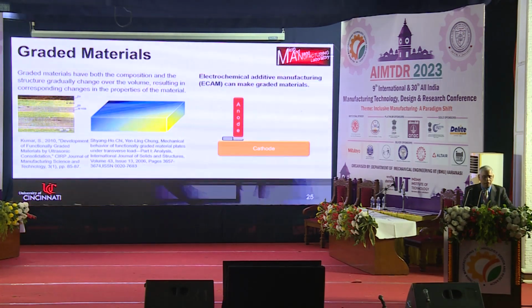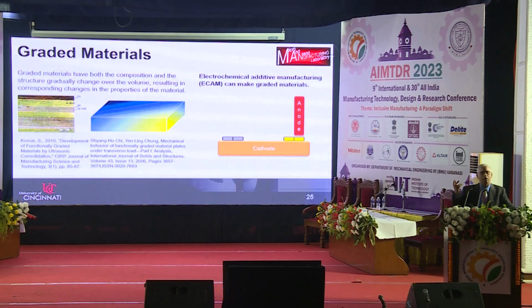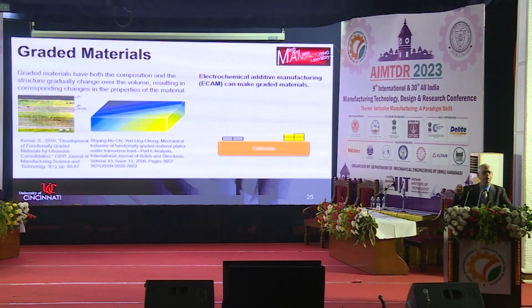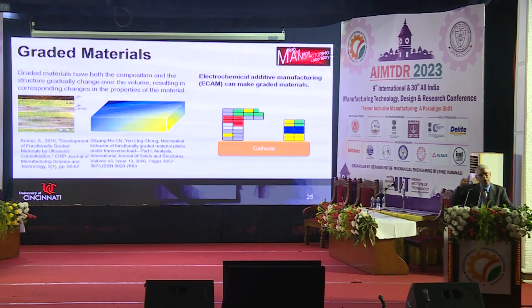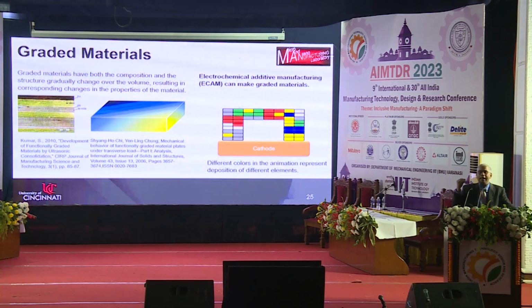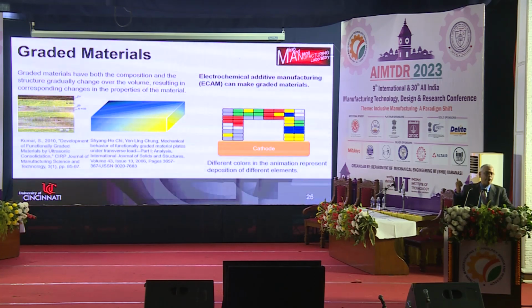So I can move my anode to whatever location that I want. And if you look at the color changing there, I am symbolically telling that is a different material, right? So I can use this concept, I can build a structure. This is going to have different materials deposited at different locations. This is what exactly is a tailored material. So it is not a naturally occurring material, you are engineering it. So it is a very, very important concept in materials design.